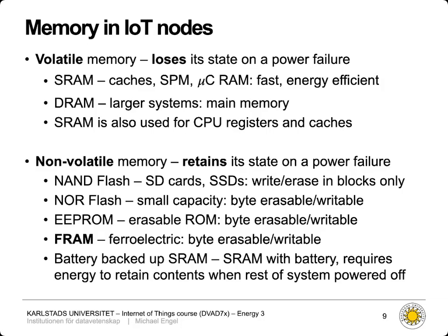In addition, doing this very many times means you wear out the flash. All flash memory is constrained to a number of rewrite cycles. So you can only rewrite a block a certain number of times, depending on the specific manufacturer and specific technology used. This might differ between 10,000 times and maybe 10 million times.